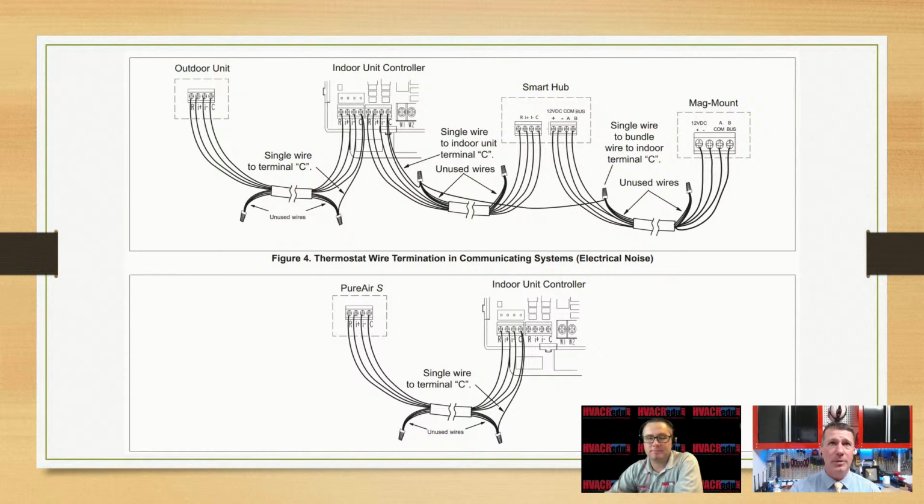When you look at the manufacturers, there's always the big question of, do I use shielded or unshielded wire? Some manufacturers will be very specific that you should use shielded wire for your communication. Some will say you can use shielded or unshielded as long as you're taking certain precautions. I've seen it both ways and I've had success with both types of wire.